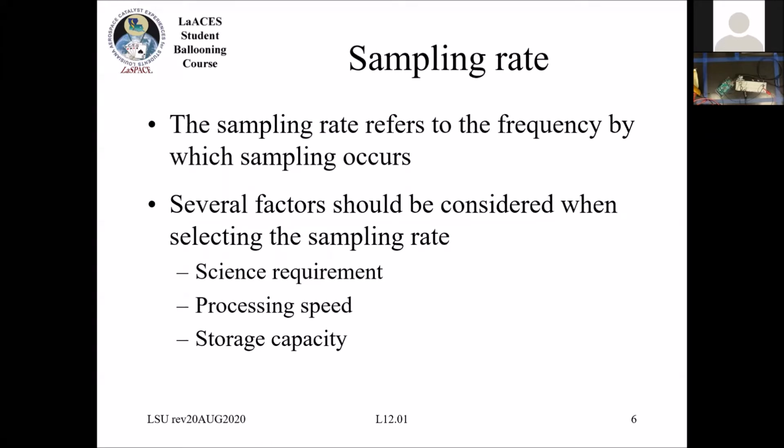And you're also going to be constrained by your storage capacity because you're not beaming these numbers down, you have to store them on some sort of permanent storage media. In this case, you will most likely be using an SD card, which is actually a very large capacity storage device. But previously, what was used was an EEPROM, where you would maybe only be able to store like 1,000 values total.